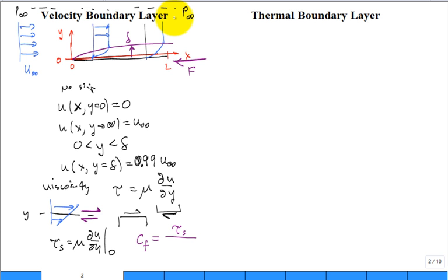Velocity pressure, dynamic pressure. What is the equation for that? Excellent. Thank you very much. 1/2 rho U infinity squared, because U infinity is the appropriate velocity that stays constant throughout our system, the velocity far away. Doesn't that have the units of force per unit area? 1/2 rho V squared. Why do we have the 1/2? You could take it out, but the majority of engineering literature leaves it in.